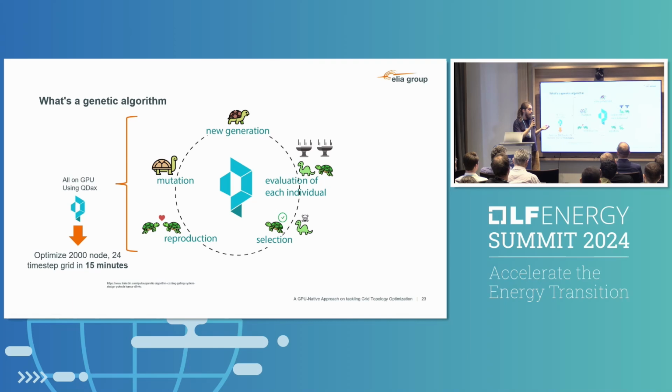And then we can also add soft constraints. So let's say if we find a topology with 4 open splits, which is just marginally better than the one with 5 open couplers, then we would probably take the one with 4. So it's a mixture of penalties and hard constraints. We can implement both. The good thing is we don't need to linearize anything. We can just compute them and then penalize them. This is a gradient-free optimization.